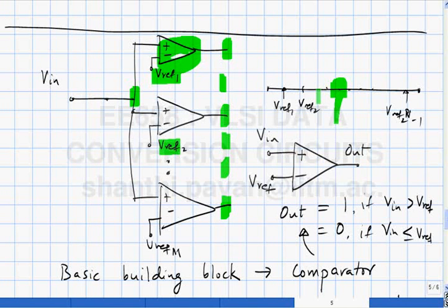An example of such converters is where you have a very high speed feedback loop, which happens all the time in communication and control. When this AD converter is embedded as a part of a feedback loop, you can't wait, because the loop will go unstable. So when you want things done quickly, that's when flashes are used. Typically, flashes are always the first converters to be done in any advanced technology.